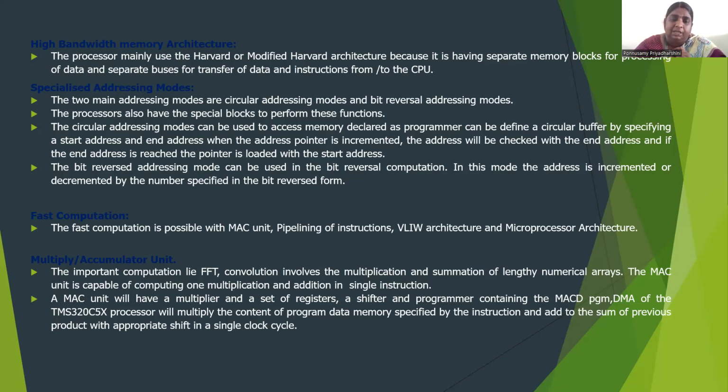And the bit reverse addressing mode can be used in bit reversal computation. In this mode, the address is incremented or decremented by the number specified in bit reversed form. Fast computation is possible with the MAC unit, the multiplier unit, and the pipelining instructions, and the VLIW architecture also helps fast computation.